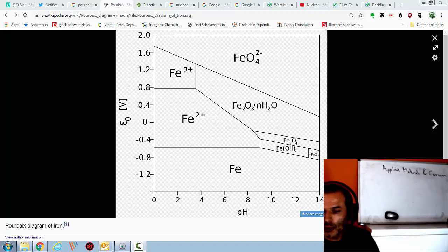So as we saw in our measurement, iron at pH 10 doesn't corrode as fast. The current on an iron electrode at pH 10, even at positive voltage, is not as high as the current on an iron electrode at pH 4, and that's because we are forming insoluble species which are getting in the way, and that's what this diagram shows us.